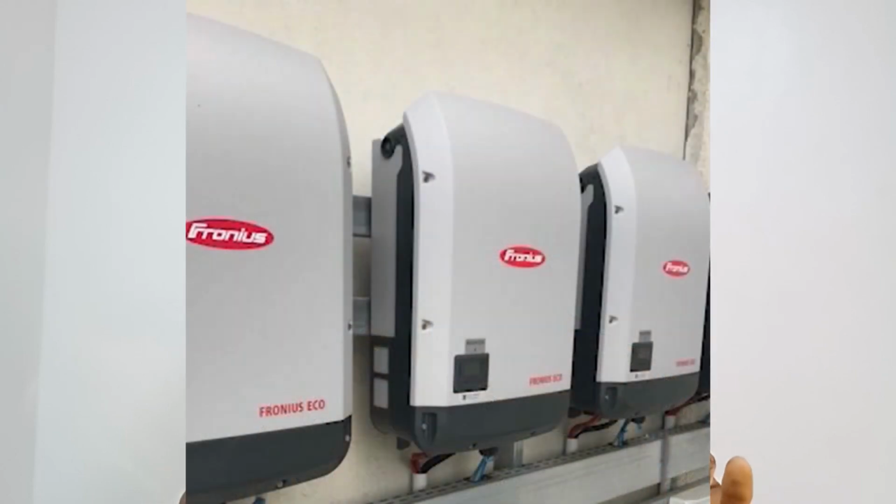Number one is the string inverter. String inverters, also known as central inverters, are mounted on the wall and have a whole array of solar panels connected to them. Under string inverters, we have hybrid inverters and non-hybrid inverters. Hybrid inverters are string inverters that have an inbuilt charge controller inside the inverter. The non-hybrid is the one that doesn't have an inbuilt charge controller inside the inverter.